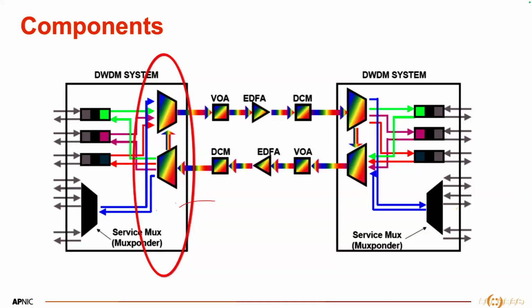You got my point? In the last study you said, no, sir, in the single mode fiber, we can have at the most 96 plus channels. Not at the most. We generally have 96 channels in a DWDM system, but we can use the ultra long band as well. We can use the L band as well. There we can double or triple our wavelengths. So the wavelengths can be increased. It basically doesn't depend on the